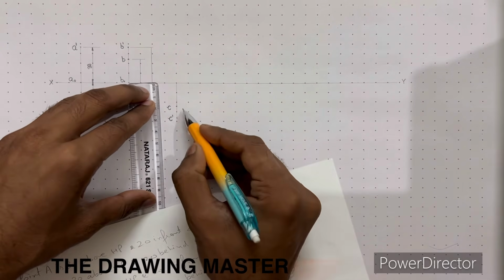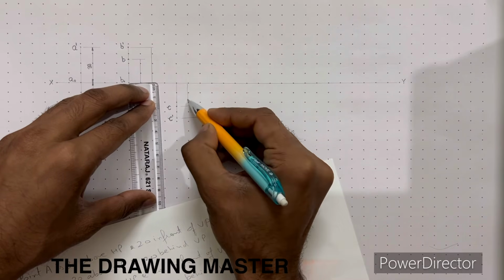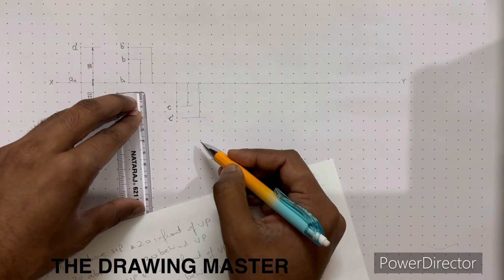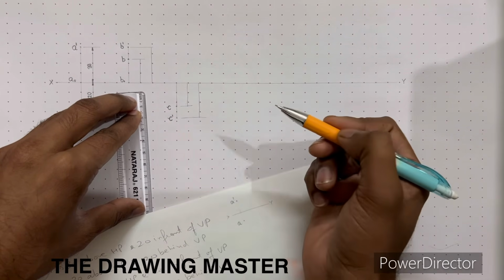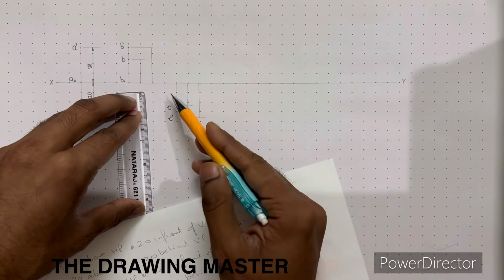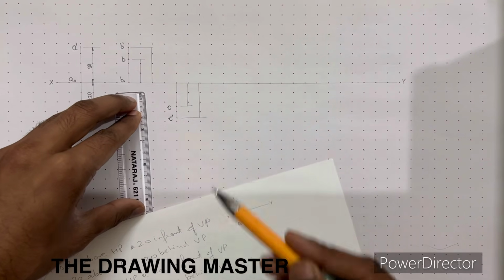Here you can write the dimensions by taking the extension line. Here take the extension line. This is the dimension line. Right? Don't write this C dash and C on this arrowhead because you are not making the projection of the arrowhead. You are making the projection of the point. Right? Follow 3 steps: reference line, projection line, label it. And then the third step, dimensioning.